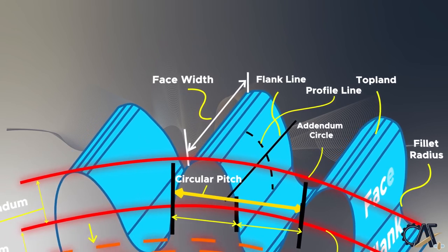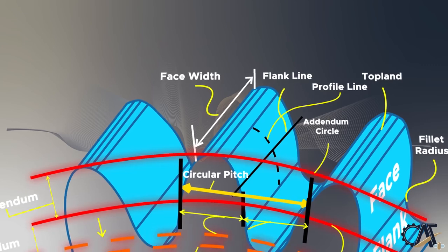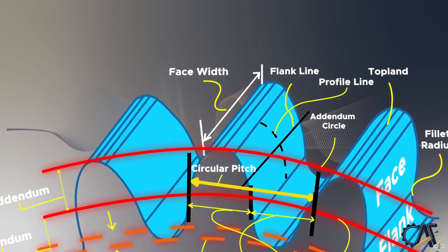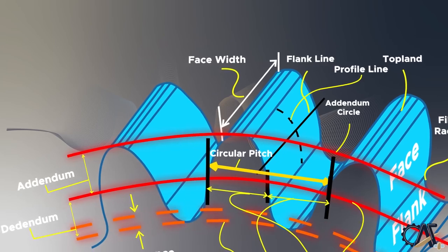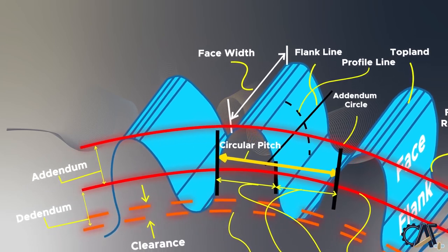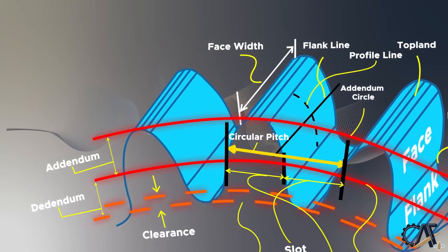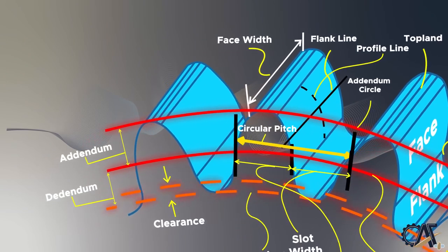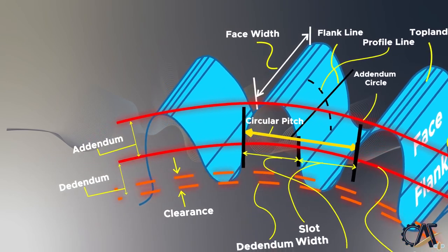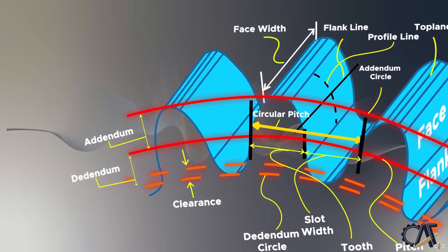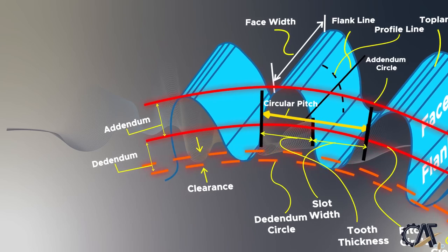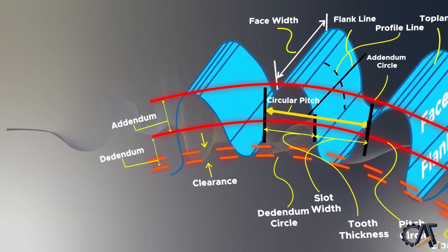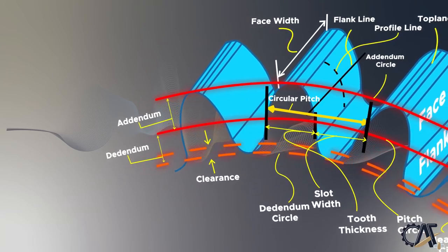The other important nomenclature in the gear profile is the gear teeth height. The height of the gear is the summation of addendum and dedendum shown on the very left of the graph. The addendum is the height by which a tooth of a gear projects beyond the standard pitch circle or pitch line, and the dedendum is the distance between the pitch circle and the root circle. The dedendum is larger than the addendum to assure that the tops of the mating gear teeth can pass the root area without interference. There are more definitions in a gear profile, but we should continue to the next step.